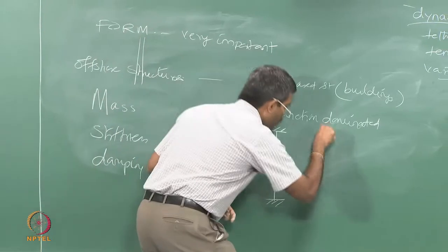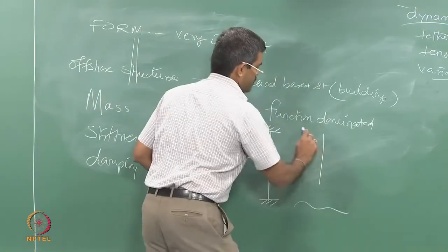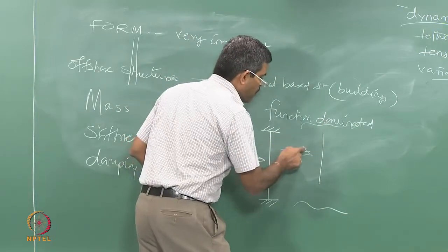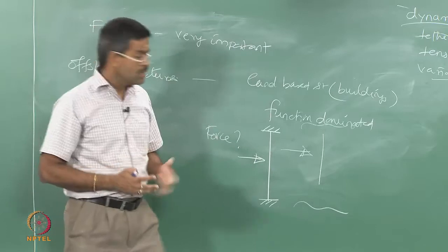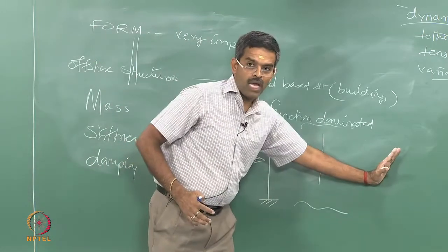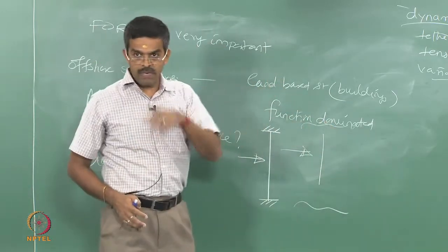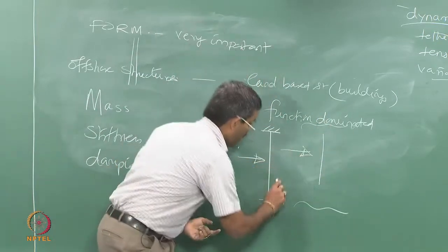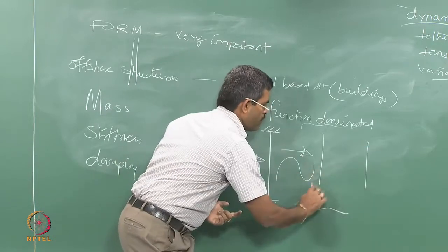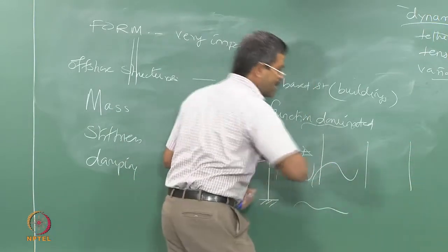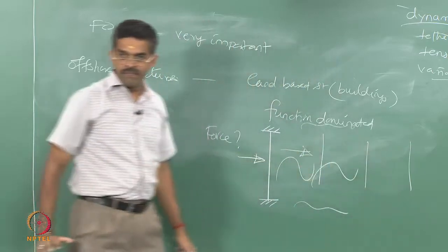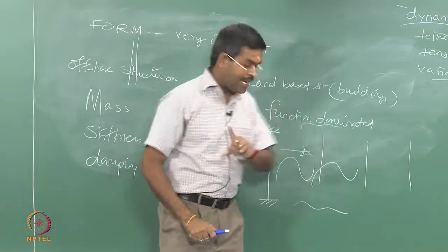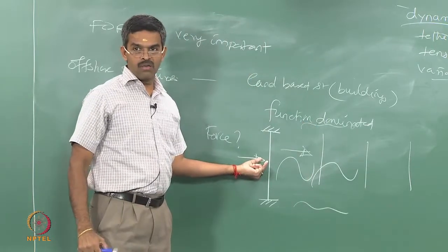If the pole is free, floating, there are no boundary conditions, the force attracted by this pole will be the least. Why? Because the pole will start moving and give way to the force to pass through the pole. It means there is a relative movement between the structure and the force. When the wave hits, the pole moves. There is a relative movement between the structure and the wave. So, this relative movement will reduce the force on the member, whereas a structure that does not move at all will attract the force.